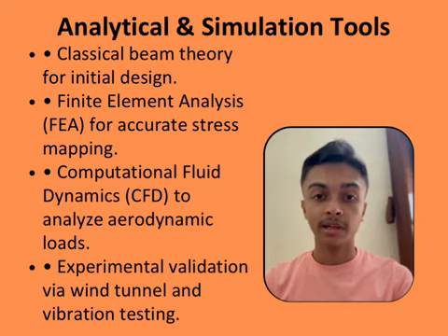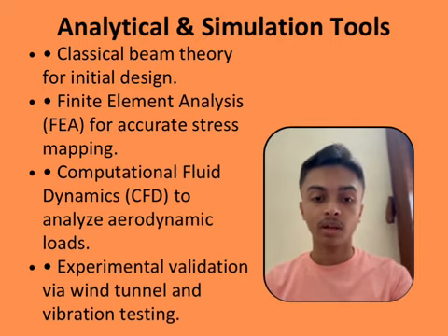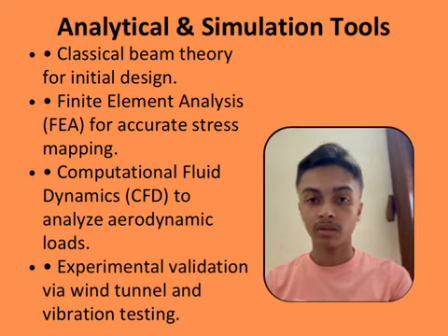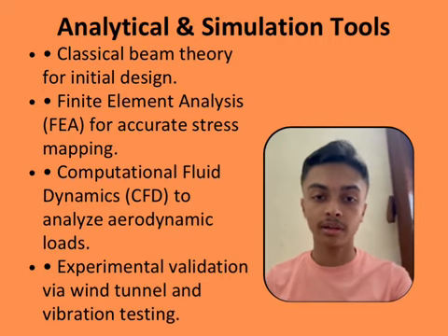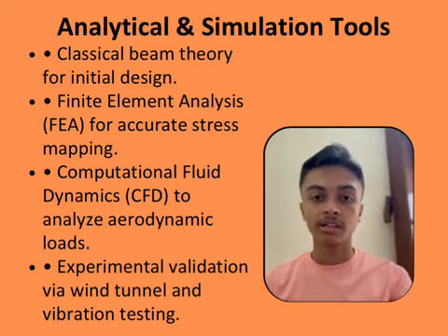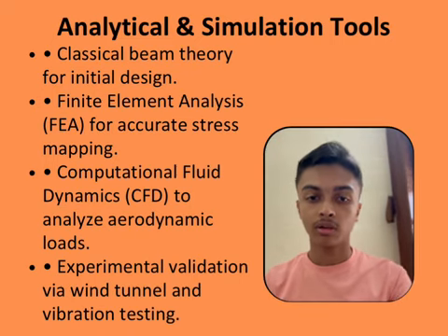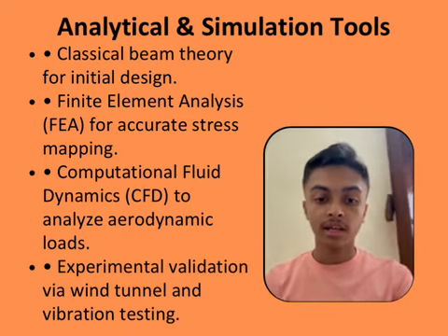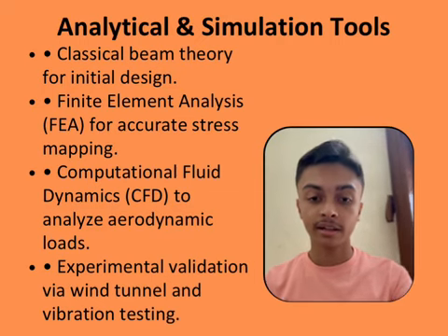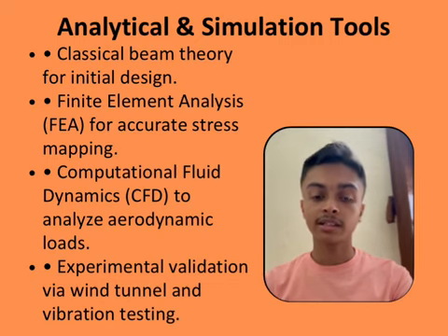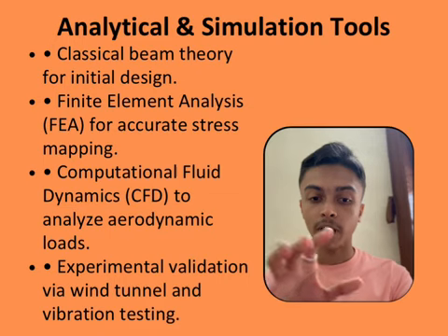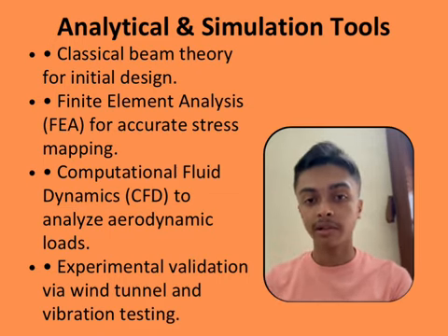Finite element analysis, FEA, gives accurate stress mapping of the structure. Computational fluid dynamics, CFD, analyzes aerodynamic loads on parts of the structures. Then experimental validation via wind tunnel and vibration testing: we can vibrate it, then test it.